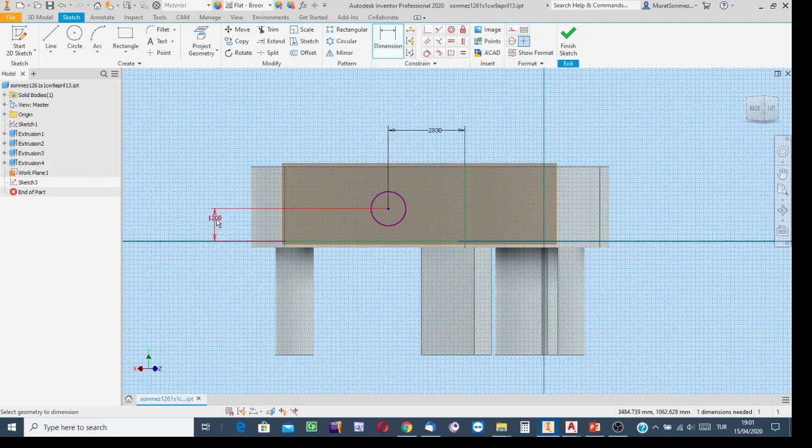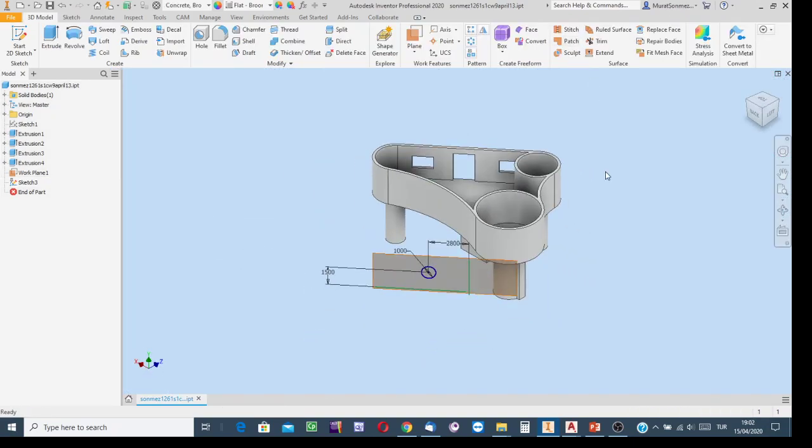Or increase it a little bit. Press the escape button. I changed the decision, so not 1200. After finishing the execution, now editing: bring the cursor onto the dimensional constraint, double click, and replace it with the new one. Say that 1500 is the new coordinate. And then size it with a dimensional constraint: indicate the circle, and say that the window is in that size. It is diameter 1000 millimeters.